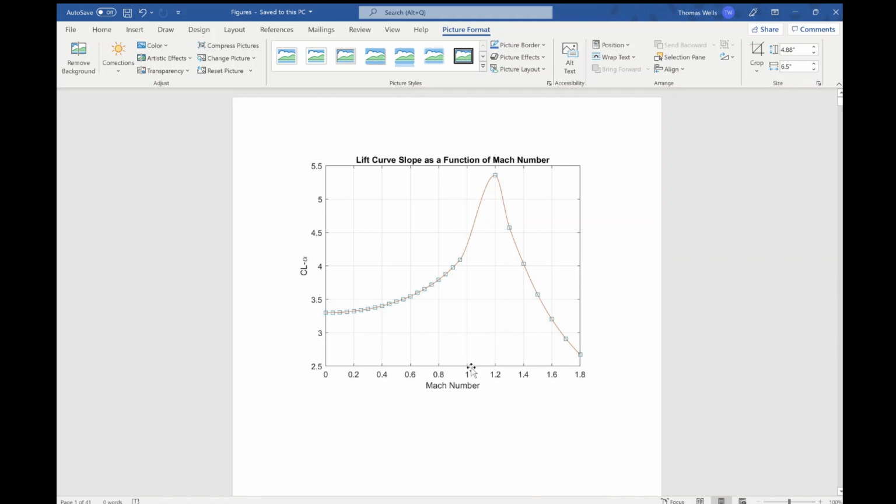All right, so looking at the graphs, in total there's about 41 of them. They cover things ranging from the aerodynamics to the propulsion inlet recovery schedule to the performance. So we'll start off with the very first graph here, which is the lift curve slope as a function of your Mach number. You can see how it will rise up to the transonic regime. It spikes here, then it'll dip down dramatically as you go into the supersonic regime.